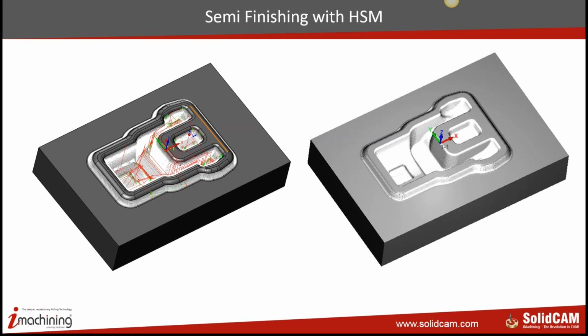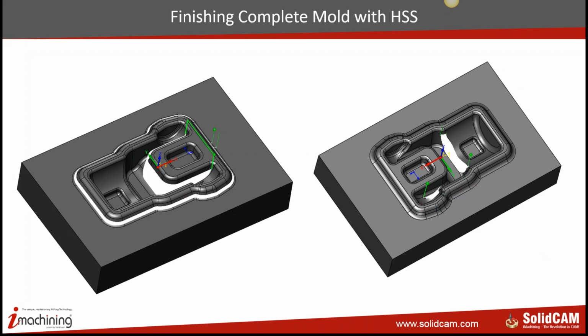So we did the semi-finishing with HSM, and then the complete mold was finished using HSS. Each of these fillets, each of those walls was taken up separately. We picked up each surface, and each surface was finished individually. People would tell me that it did take a lot of time.